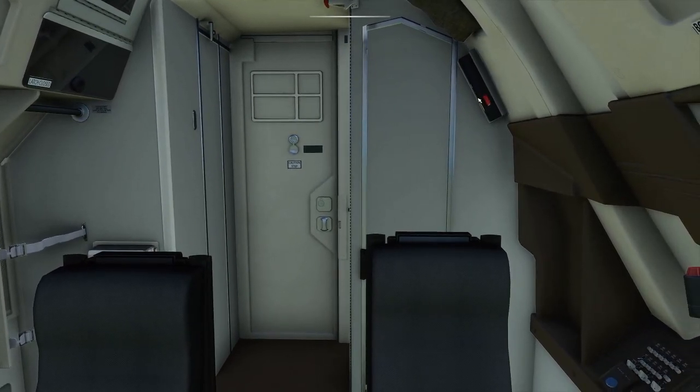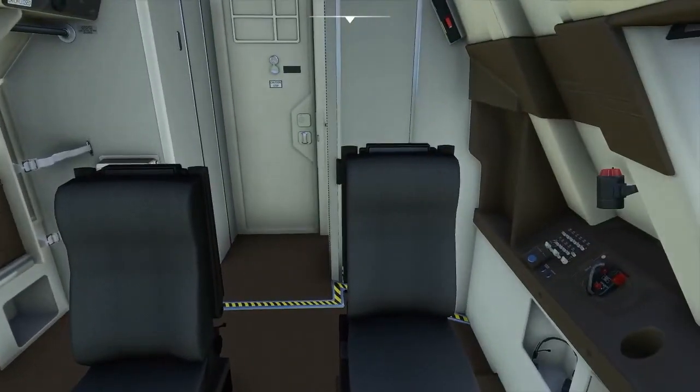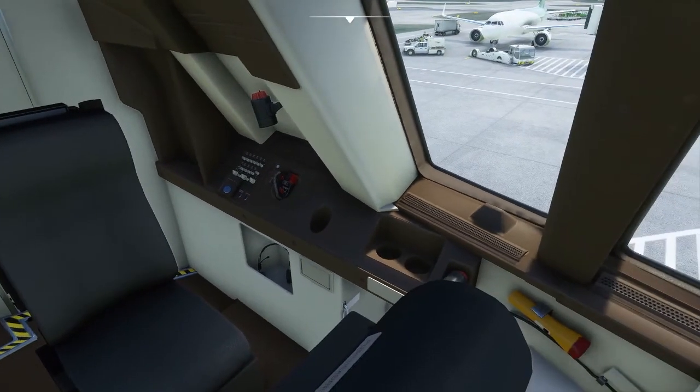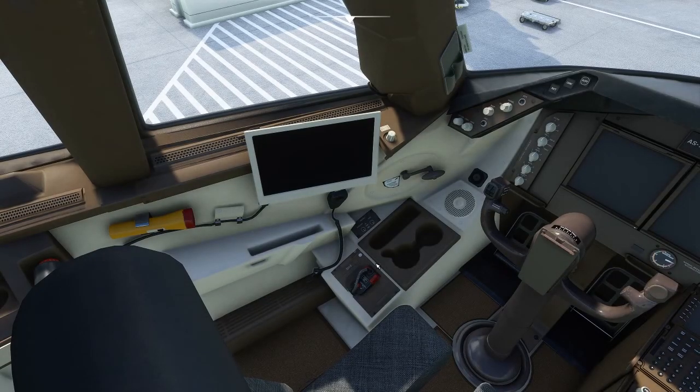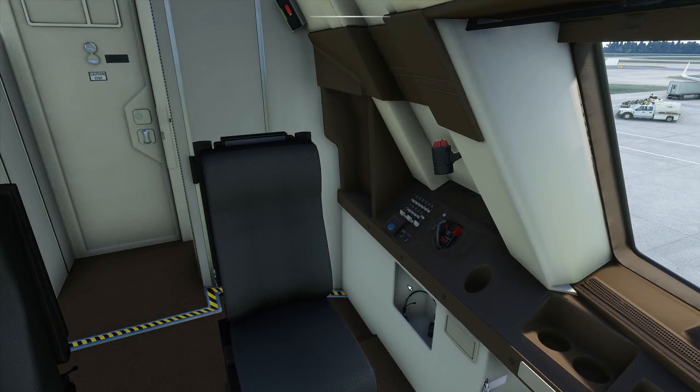This little red button is the kill switch, so they call it kill switch for the lock on the flight deck door. So whenever that's down as it is now, the door is locked, so nobody can get in or out. And you have some controls on the panel here that control the opening and closing of that. This is a quick don mask, so every seat has an oxygen mask, which is what you call a quick don. Quick don, I guess, because it's quick to put on.